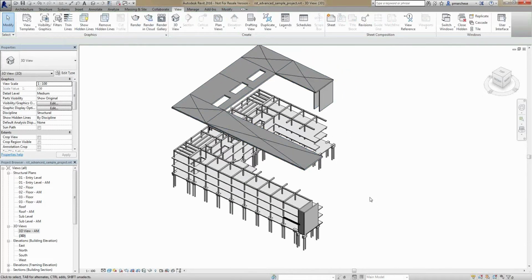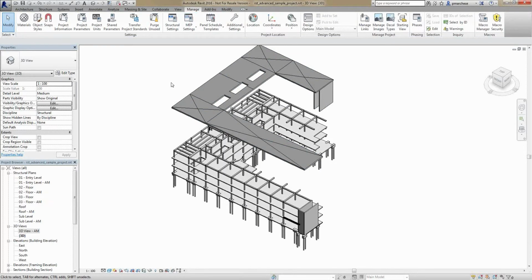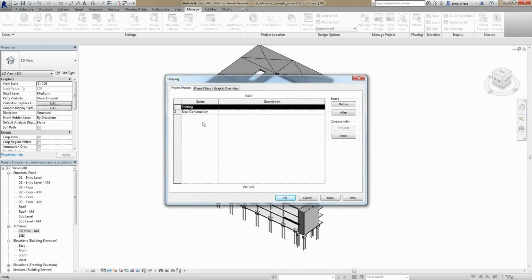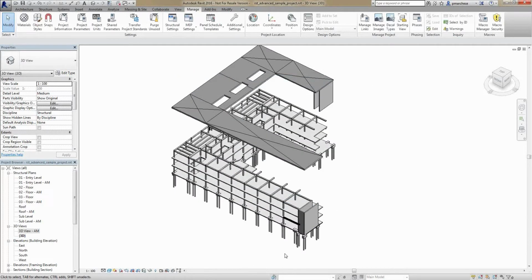Now, in terms of looking at things based on timing or scheduling, Revit does have a phase tool. And the phase tool is actually quite good. The problem that we're looking at, though, is that the phases here tend to be more along the lines of phases of construction. So existing, new, something that is being demoed would be demoed in the new construction. So it doesn't necessarily have, week 1, week 2, week 3 kind of phasing. So for that, I tend to look more into Navisworks.